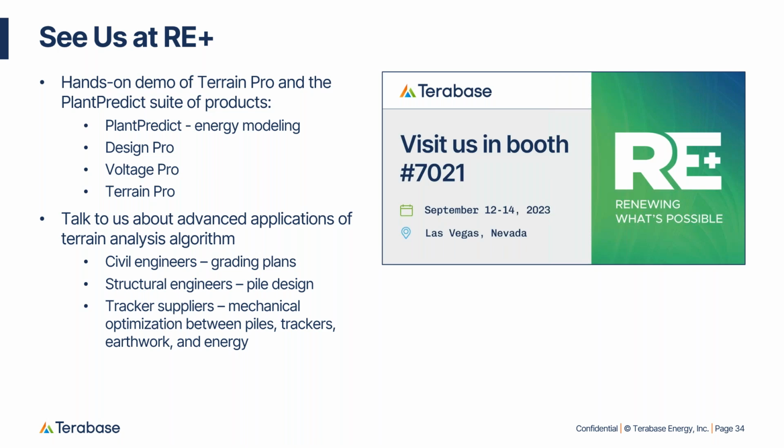The purpose of the terrain following tracker is obviously to minimize earthwork, but terrain following trackers do have limits, and articulation angle is one of those parameters that dictates how closely a tracker can follow the terrain. To optimize or minimize earthwork, a designer must iterate many times, and that lends itself very well to a software solution. Our software iterates automatically to optimize the profile and minimize earthwork.